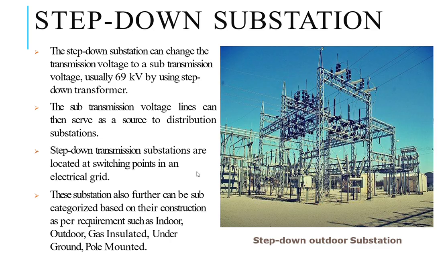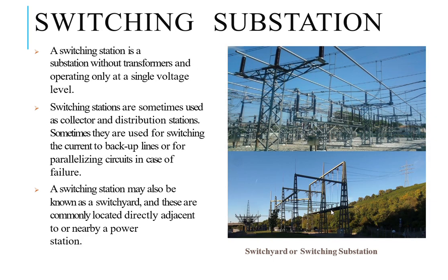Step-down transmission substation are located at switching points in an electrical grid. This substation also further can be categorized based on their construction as per requirement, such as indoor, outdoor, gas insulated, or underground, or can be pole mounted. As this picture shows a sample of the step-down outdoor substation.